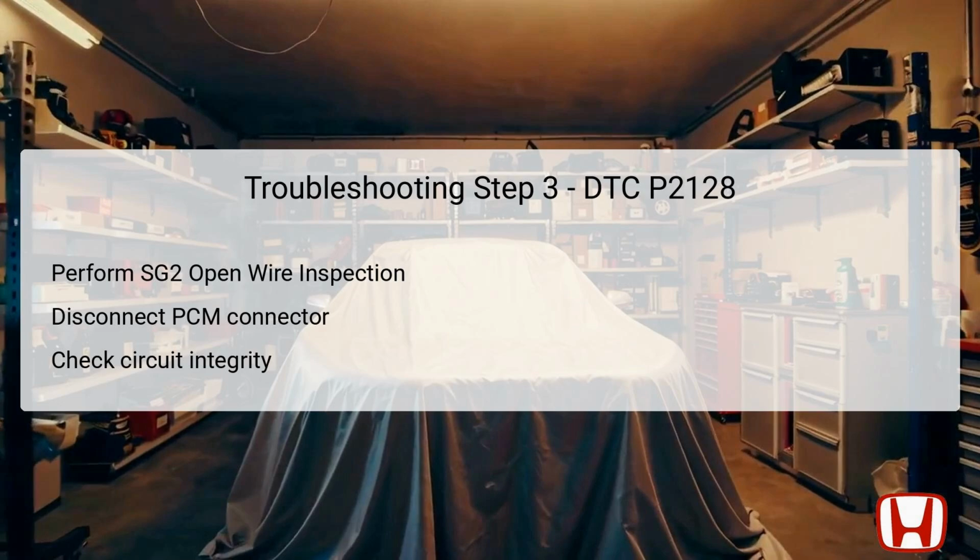This inspection process demands a multimeter to measure the resistance, confirming that it registers less than 1 ohm when checked in the off position. If resistance is measured above this threshold, it points towards a problem in the circuit itself, necessitating a more detailed inspection of the wiring and related components. Accurate assessment is crucial, as wiring issues can often lead to many performance complaints in vehicles.